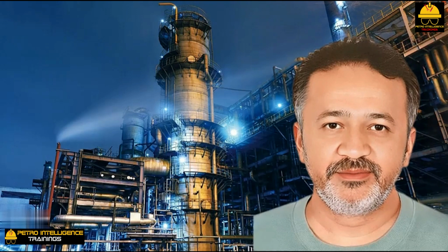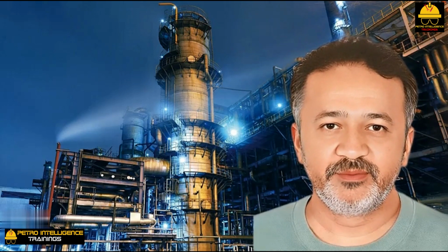Vapor binding. We can measure the non-condensable concentration in the flow of a mostly condensable vapor such as steam. However, the actual concentration of non-condensables in contact with the condensate layer around the tube wall or inside the tube is much greater. While the condensable vapor condenses and drains away as a liquid phase, the only way the non-condensables can escape from the tube surface is by diffusion backwards against the bulk of the vapor flow.